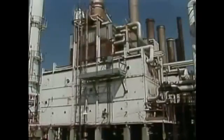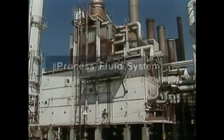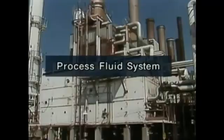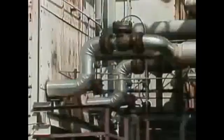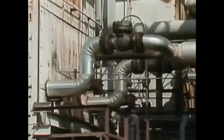So far, we've seen furnace instrumentation related to fuel supply and air supply. Now we're going to look at the process. Two main variables associated with the process fluid system are temperature and flow. The outlet temperature, in a sense, is the most important furnace temperature reading, since the main function of the furnace is to heat the process fluid to a certain temperature.